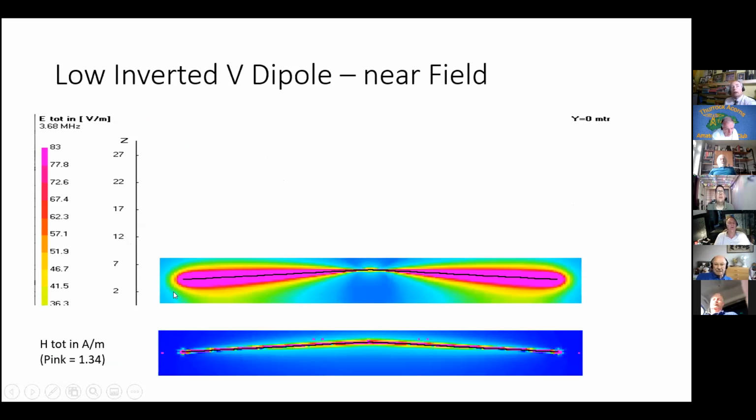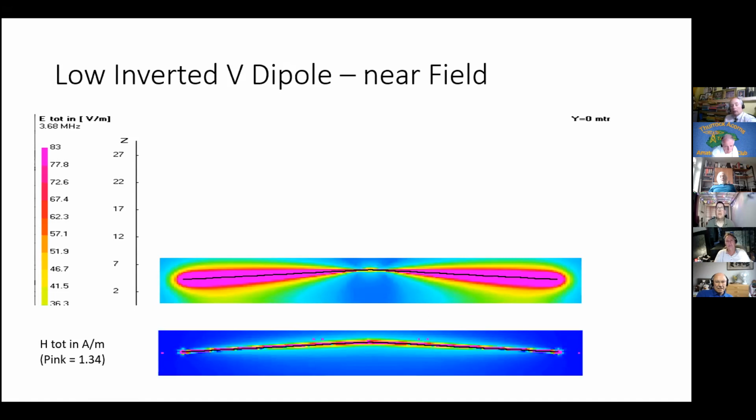So I don't have to get it any higher. The other thing to note is that because the electric field limit below 10 megahertz is fixed and low in proportion to the magnetic field limit for EMF, it's always the electric field on low frequency antennas that determines the EMF safety distance.